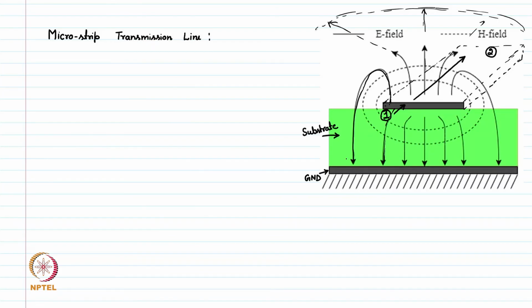Accordingly, the coupling of this ground with this microstrip is dominant. However, some portion of these electric field lines terminate at the environmental grounds or the outside ground. It means this microstrip has some amount of coupling to the environment as well.